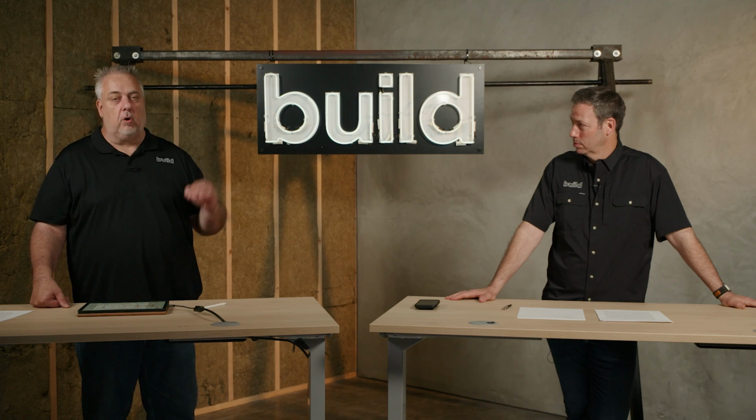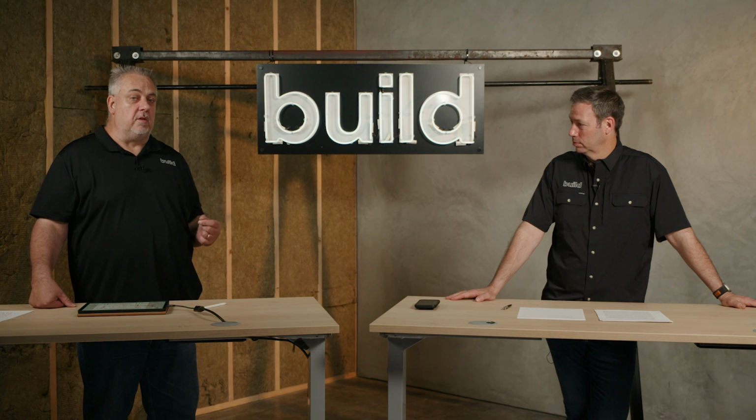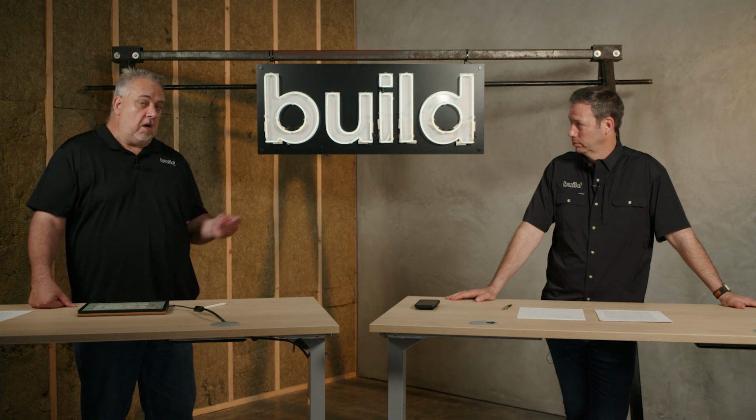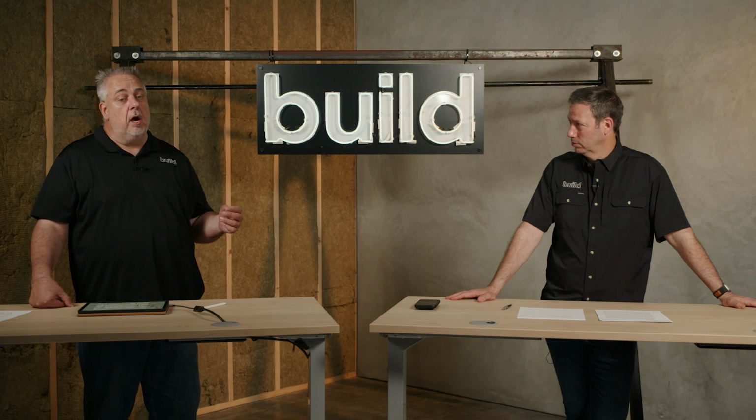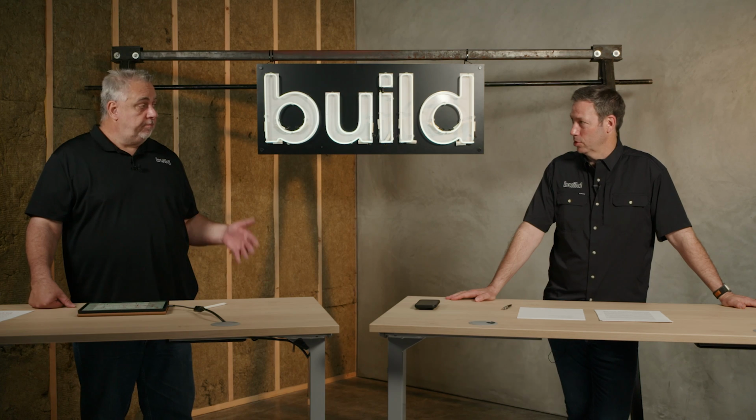So like half of my association with them is discussions in building science, because they really want to get in tune with it. But if you're the kind of client that says, hey, Jimmy the builder, just go build it, I trust you, you still should ask a few general questions of, hey, how are we going to mitigate water in our wall system? What kind of windows are you using? Do they have a weep hole system? Are you using caulk on my siding? If you are, does that water behind it have a way to be let out? Let's try a pathway out.